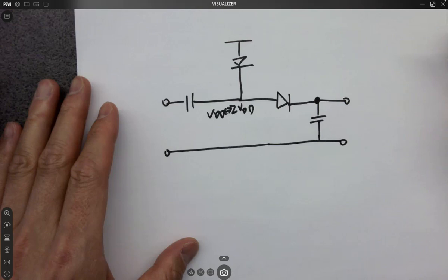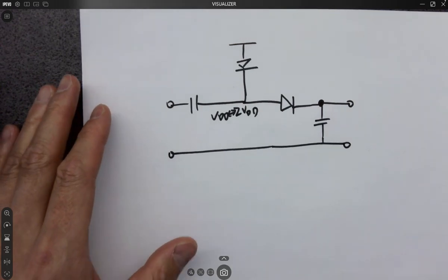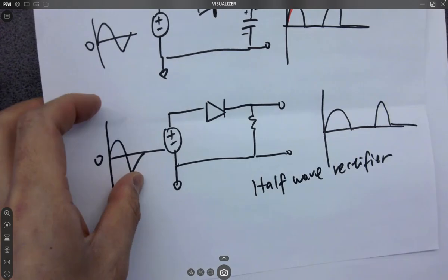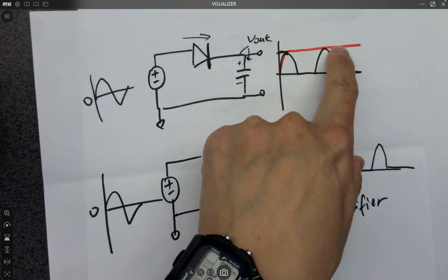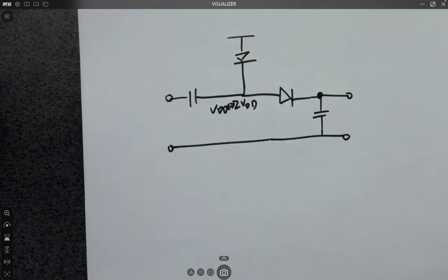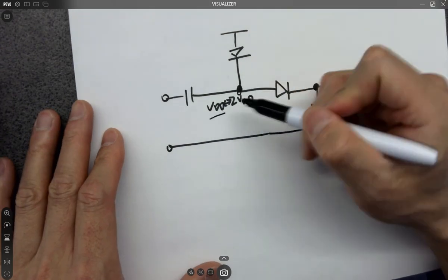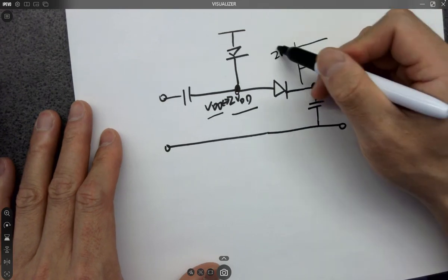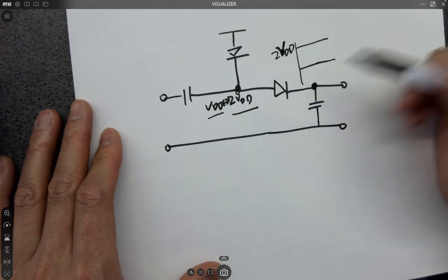And what is that DC voltage? Remember we drew that circuit, page 1, right? Eventually it becomes a DC voltage at the peak voltage, at amplitude. Same thing here. This one swings between VDD and 2 VDD, so it will give you a DC voltage around 2 VDD. It's getting filtered out. Okay, it's a 2 VDD output over here.